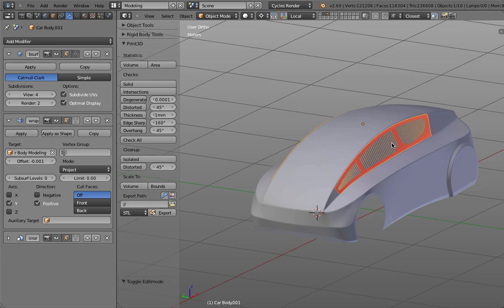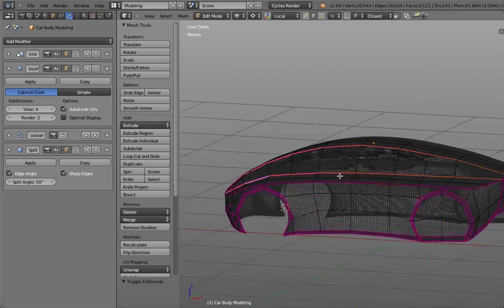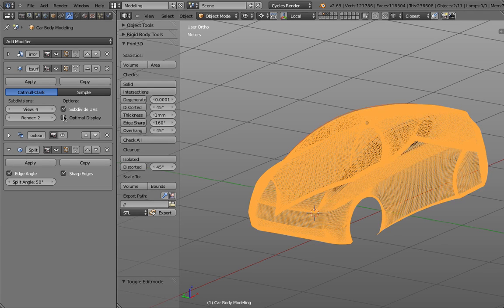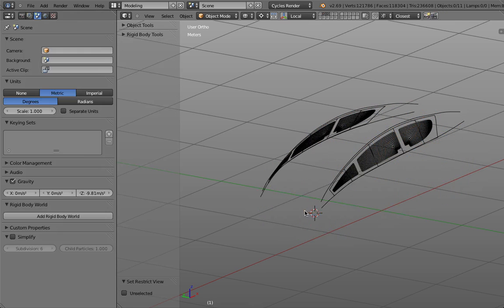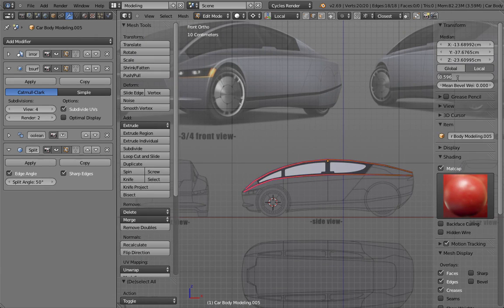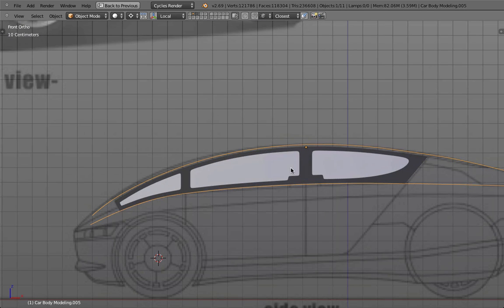So this surface, I'm going to duplicate. No, hold on. Actually, I make it different. Let's apply some good best practice. I'm going to select those surfaces here, just those edges. And you will see in a second what the reason behind this is. So I duplicate, Shift D, press Escape, press P, put it into a separate object. And there are those lines. Let's go into edit mode, select everything, and turn off the edge creasing. So here are my lines. So the lines basically are sampled from my car body.